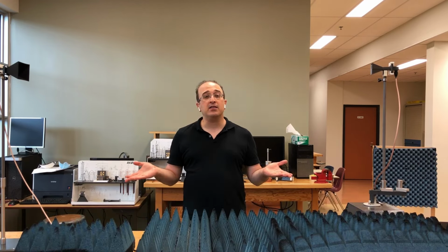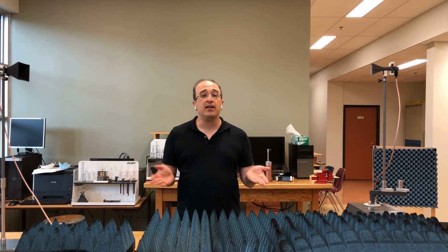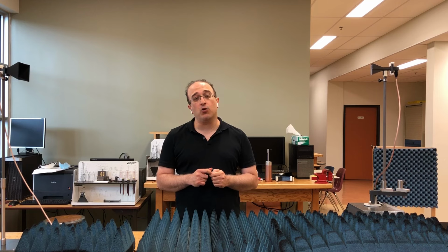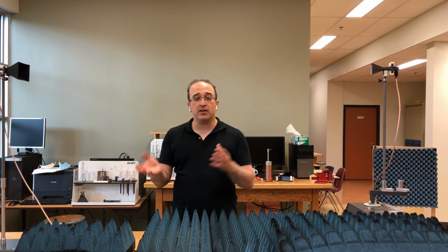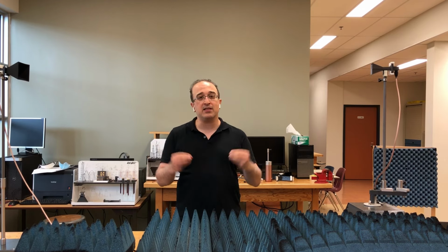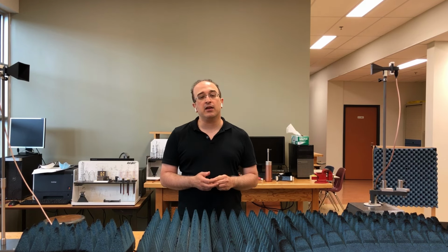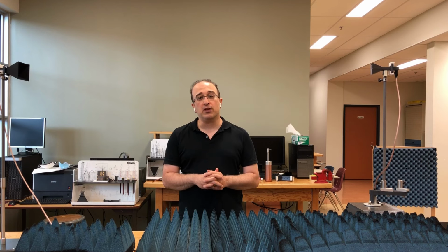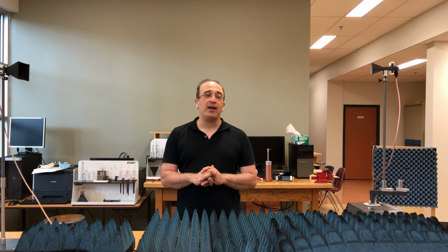So now based on this measurement, which is consistent with our patch array measurements, we're going to measure the maximum signal level of this small horn antenna. And then we know the gain of this horn antenna and its MSL. There is a relation between gain and MSL that we established. Then we look at the MSL of our antennas, and we can calculate the gain of each of the antennas that we had. And that's essentially your responsibility, to calculate the gain of the series fed and parallel fed patch array.